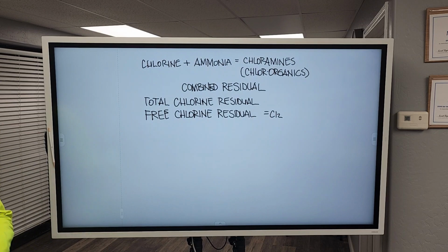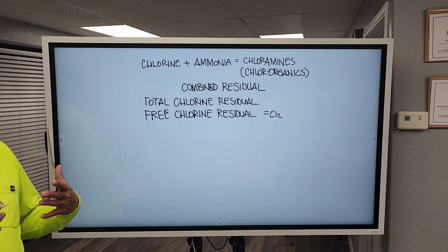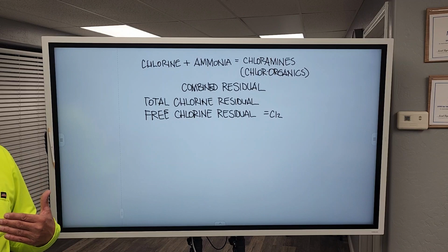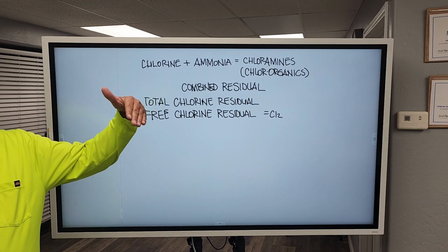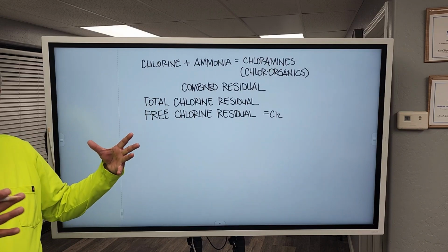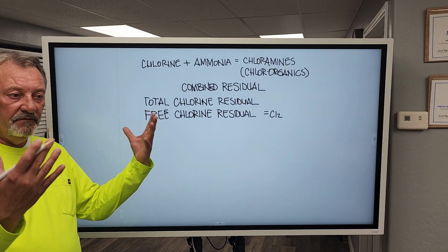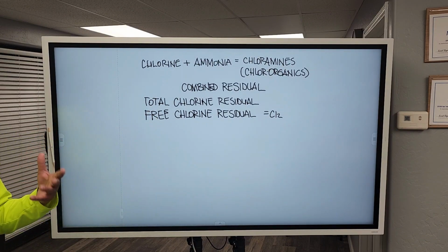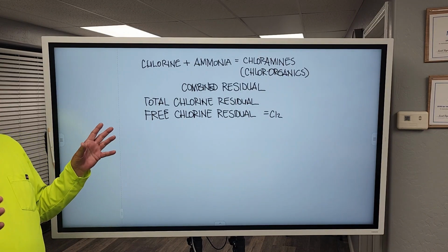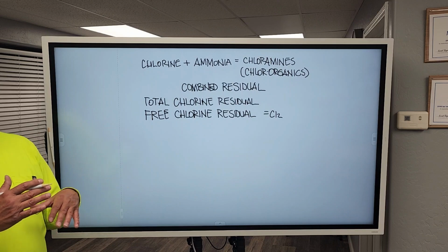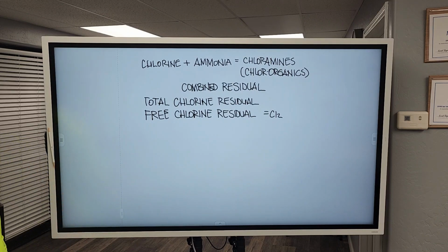Chlorine gas available in the water. It's also known as the free available chlorine, because if we have free available chlorine in the water and we're practicing breakpoint chlorination, then that chlorine is available in case the water interacts with something. If something pops up that wasn't quite there in the initial disinfection phase, the chlorine will react with it, neutralize it, kill it. That's what we're hoping for.